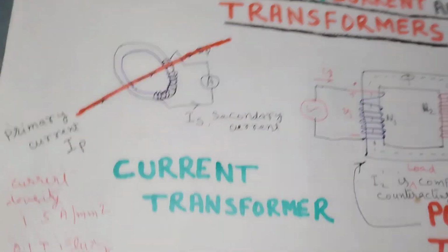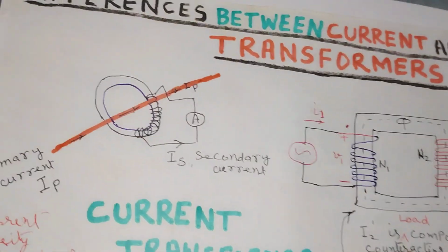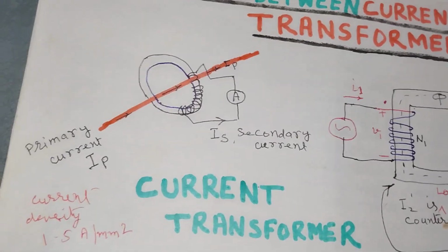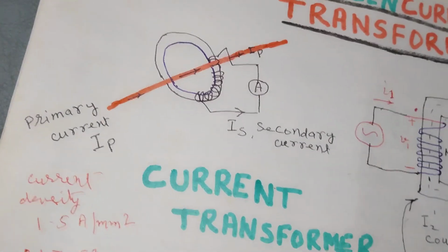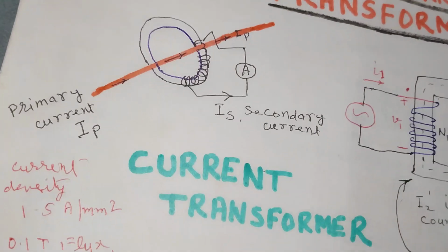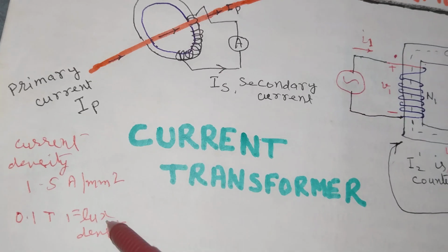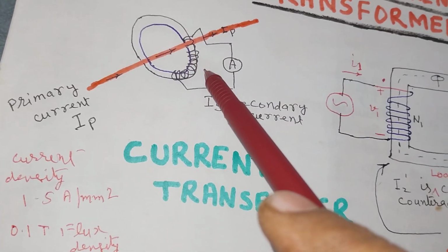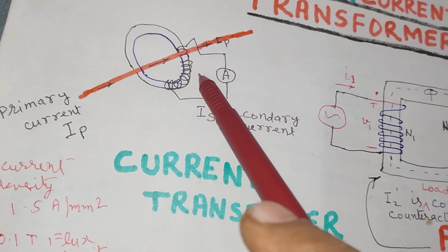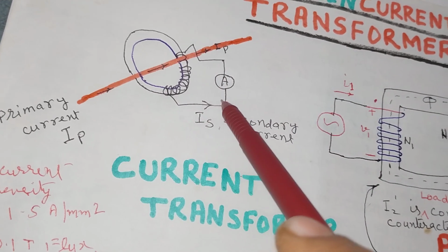It is pertinent to note that Bureau of Indian Standard has allowed 1.5 Tesla for power transformer, but for design of CTs 0.1 Tesla is selected as flux density. This is because a great level of accuracy is required in CTs.